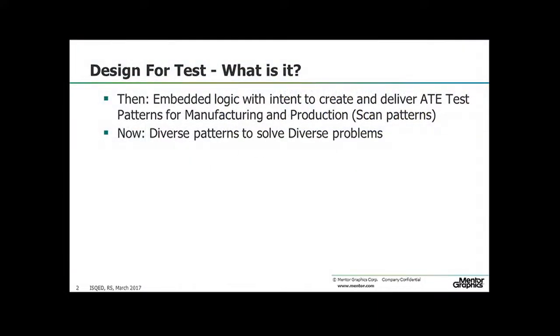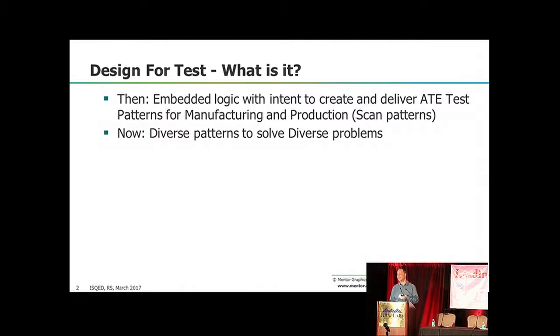So let's define DFT. What is DFT? DFT is the act of adding non-functional embedded test-only logic into your device with the intent to generate patterns for delivery to the production ATE. As these devices have got more and more complex, so have the types of patterns and the content within.